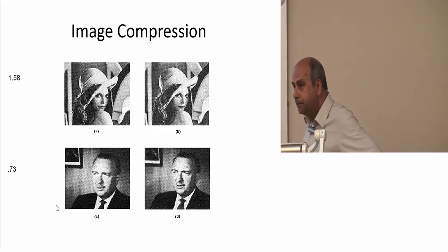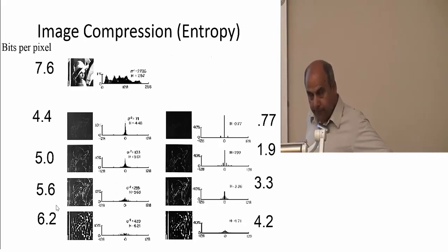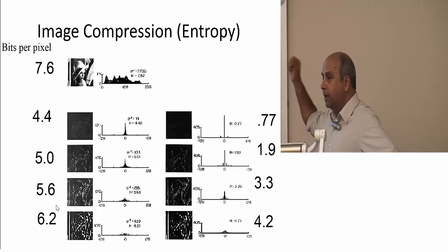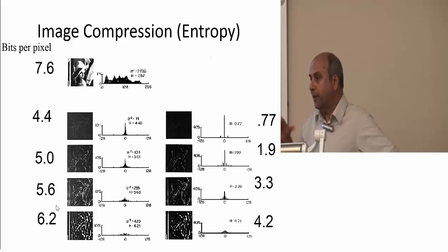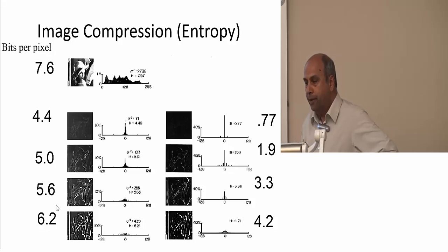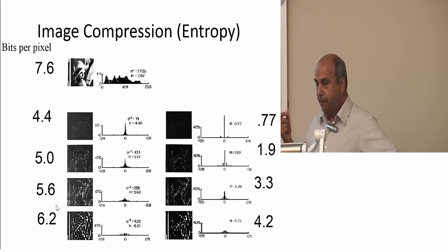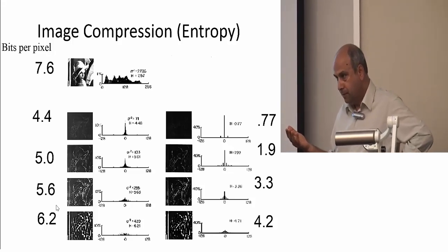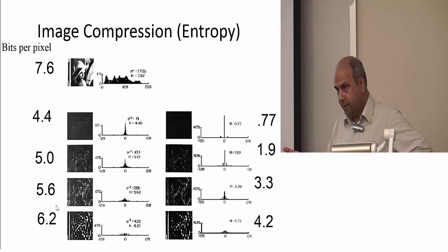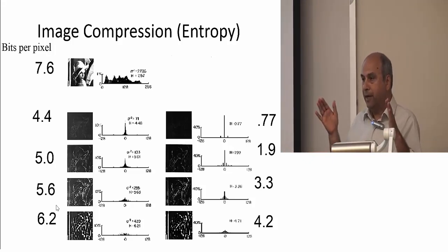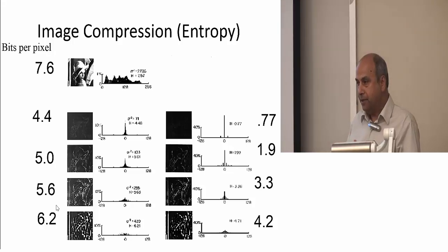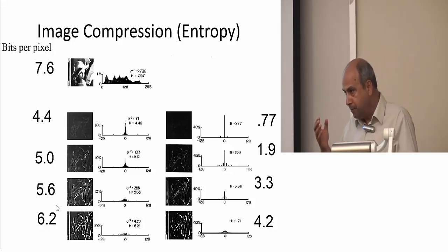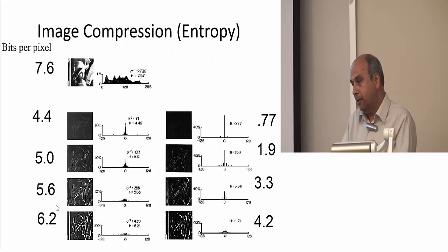In the previous slide, what was the last column and what happened there? This one? Yeah. So what we did was quantization. As you know, your homework and the exam and so on are 100 points. To represent any number between 0 and 100, how many bits do you need? 7 bits, yes? Now what I do, take the 100 and quantize it to grades A, B, C, D, yes? How many bits do you need? 2. So that's called quantization.